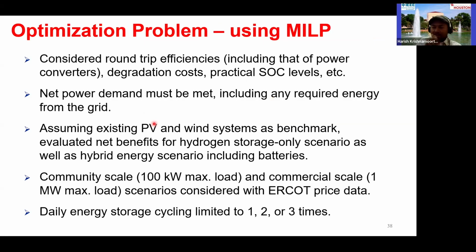So our algorithm was able to handle these scenarios in such a way that, remember, the number of cycles affects the life of the battery storage. So we made sure that we do not let the energy storage systems cycle fully more than 2 or 3 times a day. So we restrict the cycling of energy storage systems to 2 to 3 times. And we try to understand, once we add that energy storage system, how much benefit it can provide to the operators.